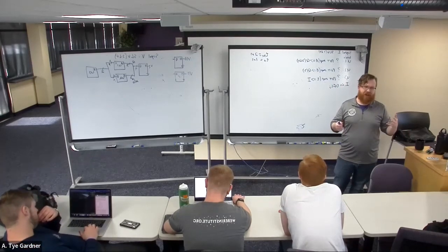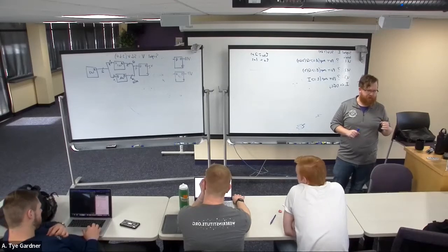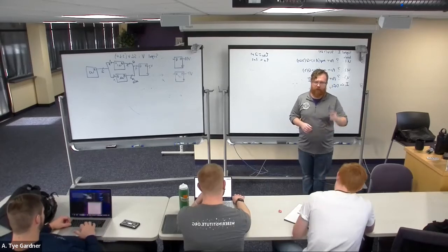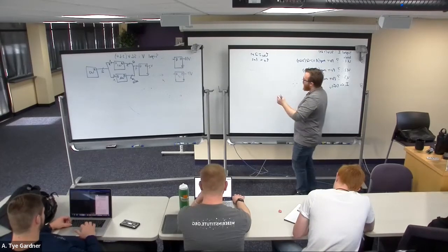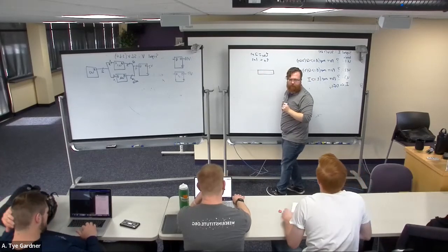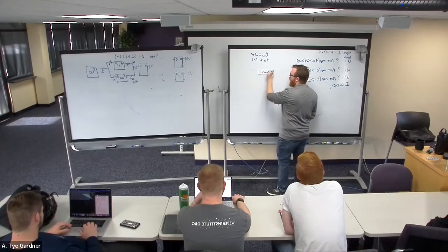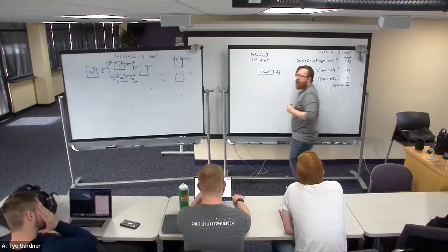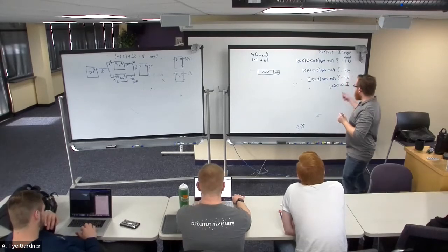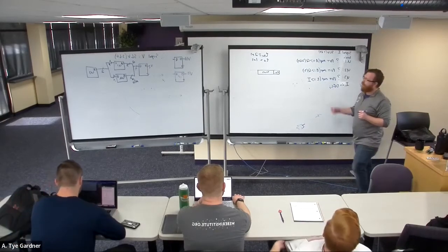That's going to have 5 8-bit inputs. Well, 9-bit inputs probably, right? Because your output sum has the carry out that you have to deal with. That being said, remember on a carry out, if I have a standard logic vector, it is a sum. The carry out is the biggest bit, right? So if I wanted to combine 2 signals, one of them is a carry out and one of them is the sum.